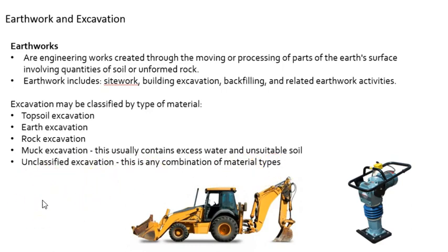So when an owner puts out a bid, essentially, for contractors to come and do excavation work, they might classify and say, I am looking for a bid for you to remove the topsoil. They have classified that it is topsoil, or they classified that it is rock. But if an owner doesn't know or doesn't want to be specific, in fear of maybe making an error, essentially, they could say that it's unclassified, and whatever materials the contractor comes upon while digging, they are responsible for removing.